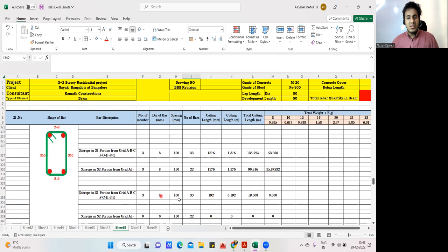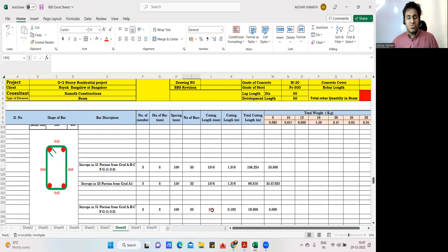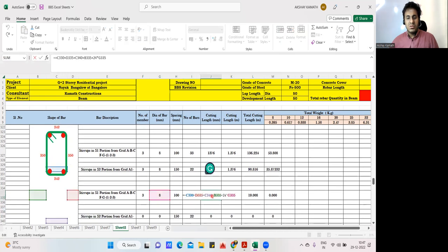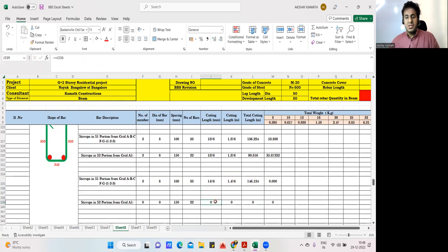In the cutting length, the change will happen. Okay. So in the cutting length, this will be 400. No. So where is my cutting length? This one. Okay. So I'll directly write the cutting length here instead of doing that. Plus 242. I'll manually write plus 242. You're getting no? Plus that will be 400. If you're doing 450, this will be 400 and 400. Okay. Let's enter, finish. It will be 1476, obviously, because 100 mm simple. From here, 100 mm axis will come, and this I'll interlink with this. Okay, done. I think rest all things will remain same.